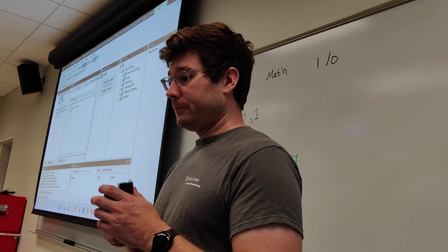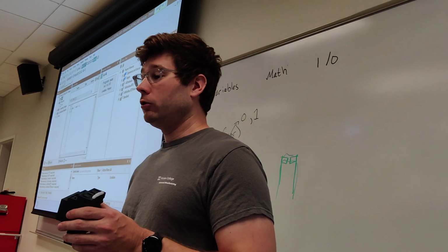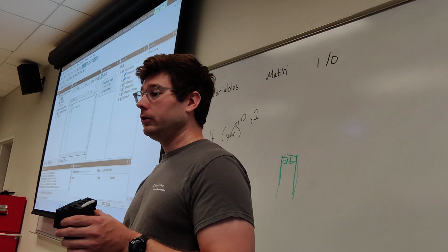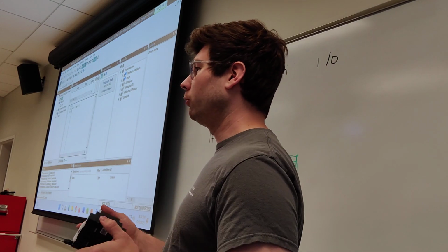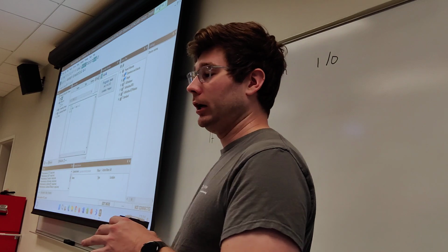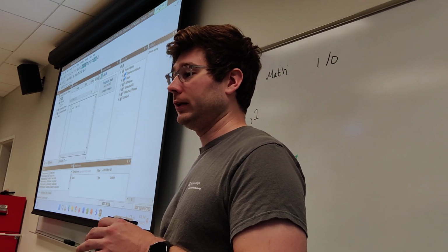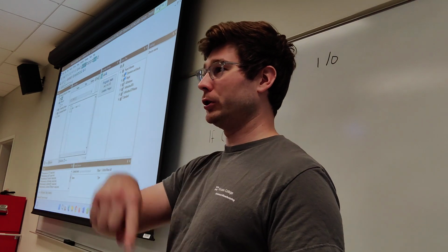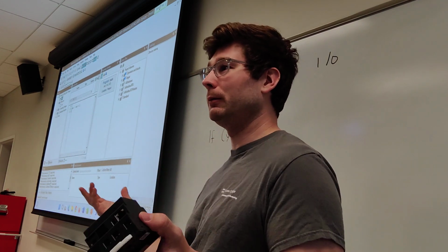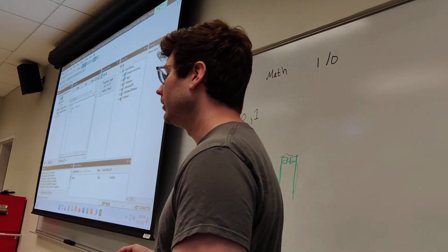Yes, when you click download PLC code, you don't have to recompile. It automatically clicks that button for you. So if you change your code and hit download PLC code, it hits the compile button to recompile the code and then pushes it to the device. So you're not going to be uploading old code or something weird like that.